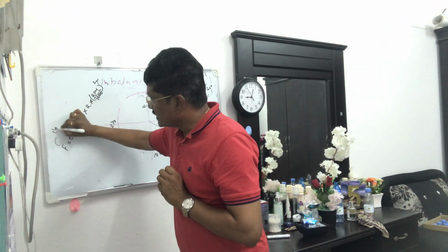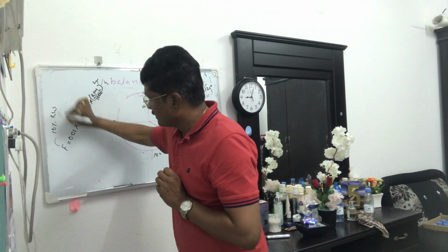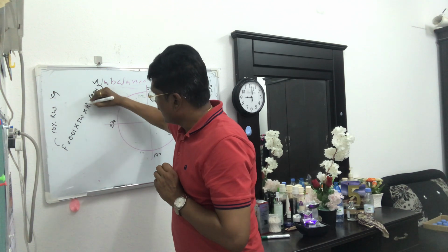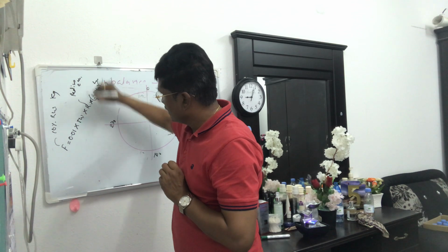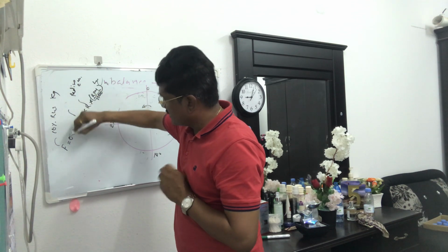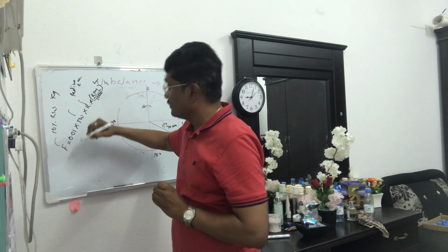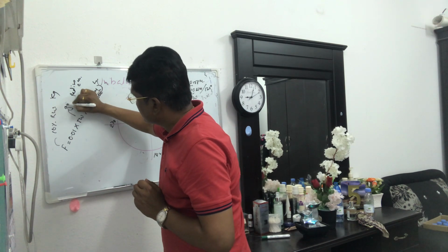F means 10% of rotor weight in kg. R means radius in centimeter. Trial weight means the actual trial weight we have to add, in gram.